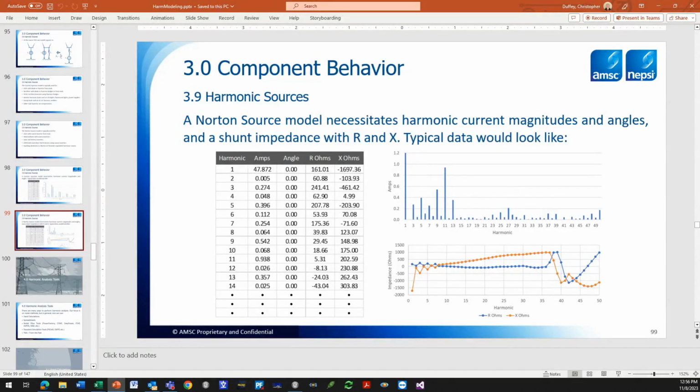Okay. Are you considering arithmetical summation to calculate total harmonic current at the grid entry point? So total harmonic current at the grid depends upon how you want to choose to look at it. Because I'm doing a 519 compliance check, I would choose the basis according to the 519, which is maximum demand current for the plant. And so as you saw in this spreadsheet,